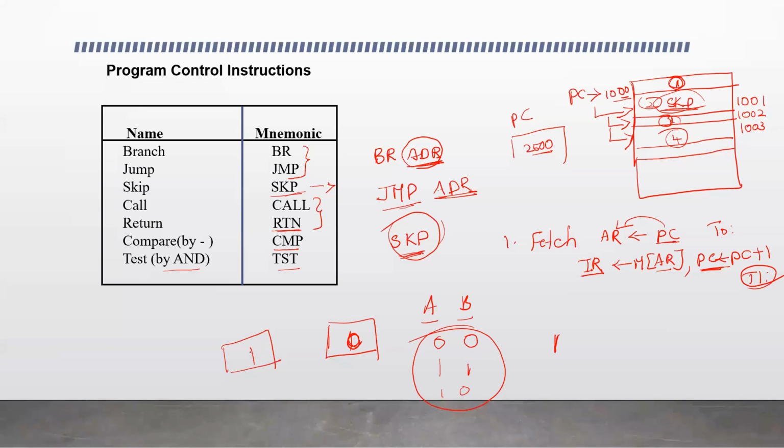So by this we can find out, in case we want to find if both the numbers are positive, the leftmost bit is checked. It performs AND and based on the result of AND, it sets the status flag. So these two instructions, compare and test, perform some operations on the input operands, and based on the result of the operation performed, they are used to set the status conditions. Based on the conditions, the control flow of the execution can be controlled.